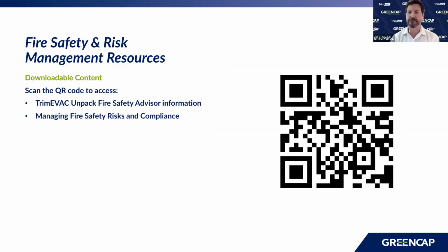Chong Chi? Yep, I think it is very important. Remember just now when I showed the slide of travel distance and all that, when the travel distance changes in a building, that would mean that you need to travel extra metres to get to the exit. So if the arrangement of the venue changes the paths of travel and extends the travel distance, that needs to be looked into. And we have seen places where certain events take place and certain exits are not allowed to be used, and then there's an alternative route. Those need to be addressed as part of that event to make sure that you still comply with the very basic design intent of the building, so there's no extended travel distance. So yeah, it needs to be assessed.